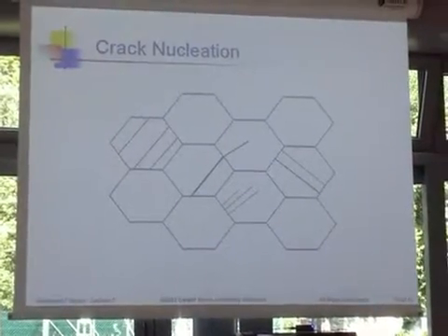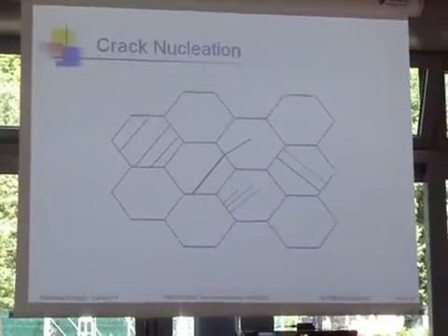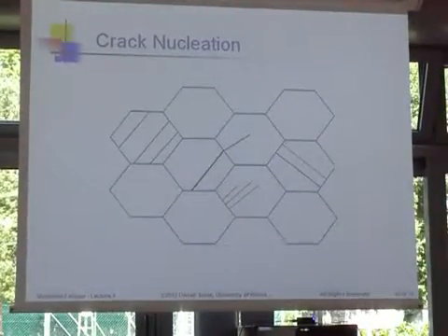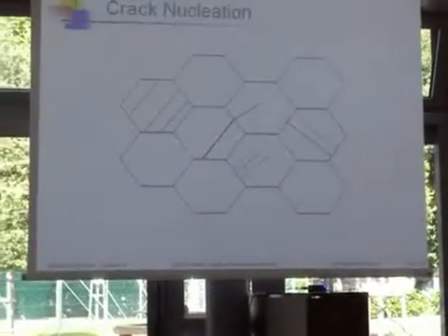And let's think about that I load this, and I'm going to load this in this direction. So I'm just going to pull this in tension and push it in compression. So we already talked earlier today that that's a non-proportional loading case, right? Because the principal stress directions change, right? But we recognize it as the simplest uniaxial load case. And if I looked at the picture, I might see something like this.